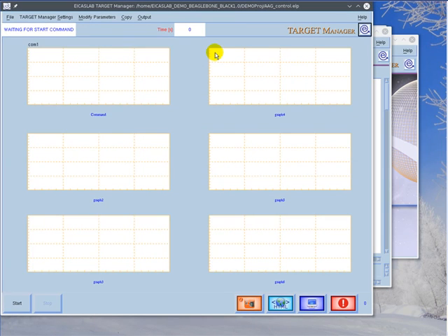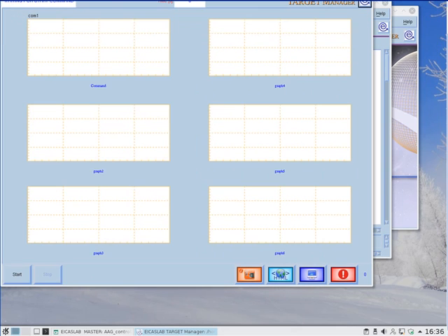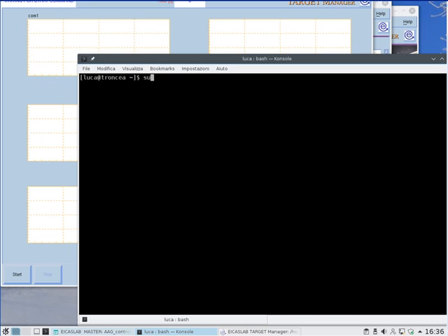For performing the trial, we will have to run the already compiled board control program using a remote session on a terminal. So let's open a terminal. We have to log in as root user. Then we log in remotely to the embedded target using the Secure Shell protocol.